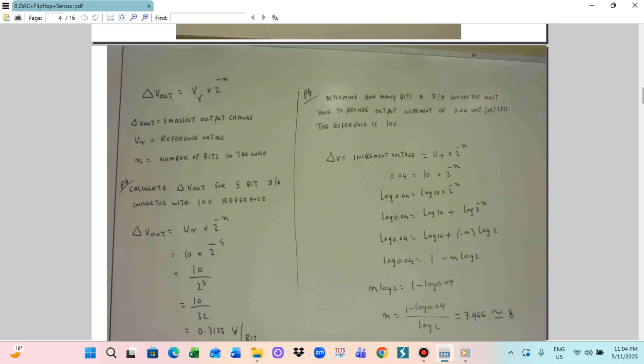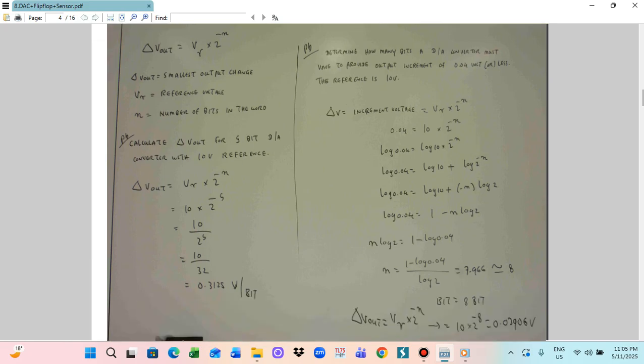Okay, at this stage we are talking about the digital to analog converter. When we use a computer control system, the computer produces a control signal in digital format, and this digital format is converted using the reference. So V out is equal to VR multiplied by V1 2 power minus 1, V2 2 power minus 2, up to Vn 2 power minus n. This formula calculates the analog voltage depending on the bits: bit 1, bit 2, bit 3, up to bit n. V out is the analog output voltage, VR is the reference voltage, and V1, V2, V3, Vn are the n-bit binary word. So this is one equation.